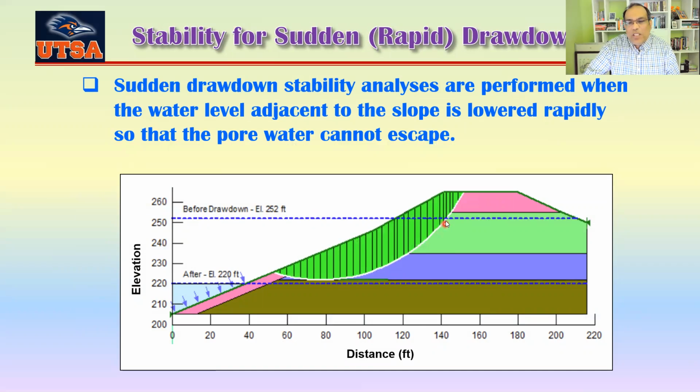This one was there for a long period of time, so this force will cause, you can see there's a lot of force here compared to here. So here the consolidation will be much higher than the consolidation that occurs here because the load here is much lower. Okay, so in the first stage we try to see how much consolidation has occurred there, okay?